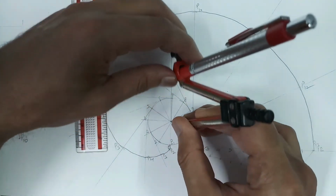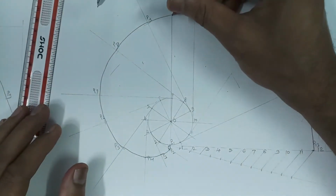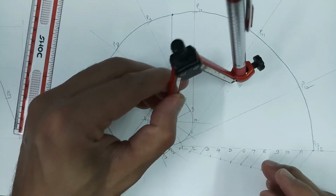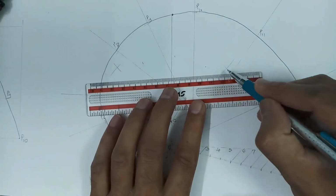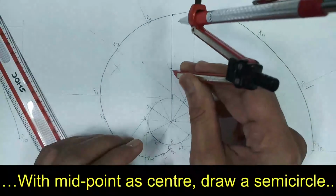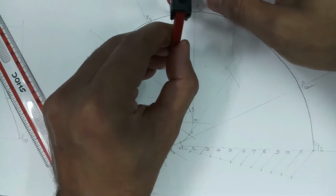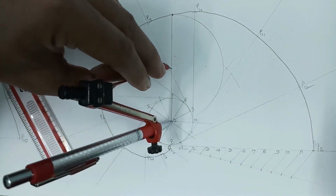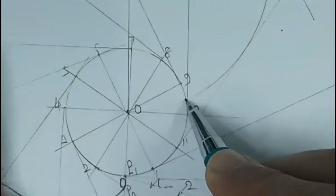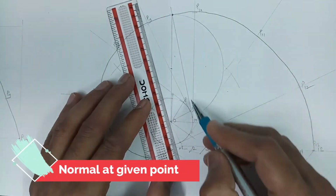You know the procedure to mark the midpoint. We have to take a distance more than half in the compass and draw two arcs on either side. Put the pointer at this point and draw another two arcs, something like this. Then join this point and this point. So this is the required midpoint. With this midpoint as center and this much as radius, draw a semicircle. Now wherever this semicircle intersects this circle, we have to join this point with the point under consideration. So if I join these 2 points, this is the required normal.